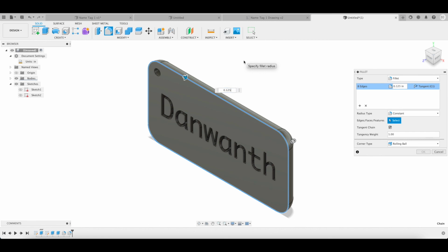It's not going to let me fillet it because, and there's an error. It just popped up. So that's because it's going to go into the other fillets and interfere with some stuff in the geometry. So if it interferes with it, it's not going to let you do it. So to make it not interfere, we're just going to go 0.05, smooth enough for us, and we are good.